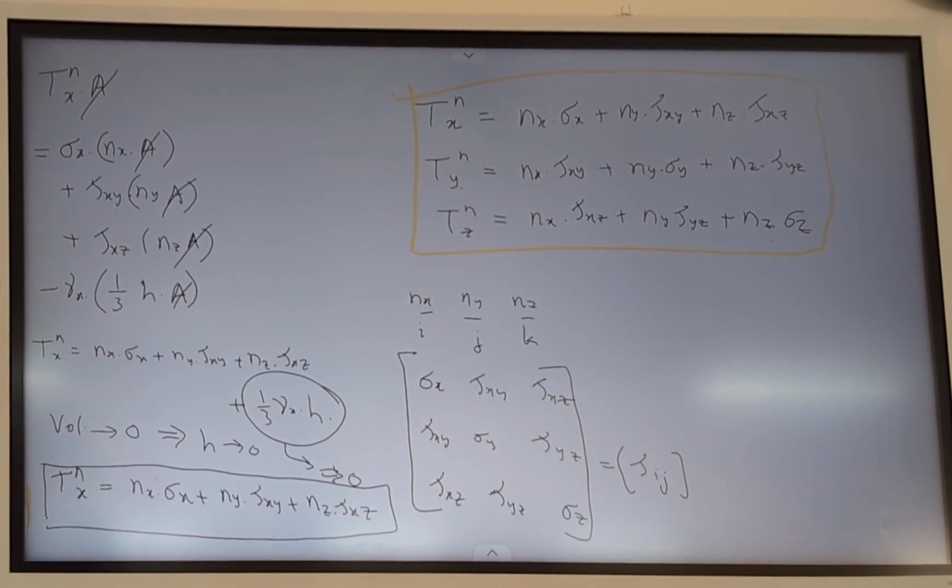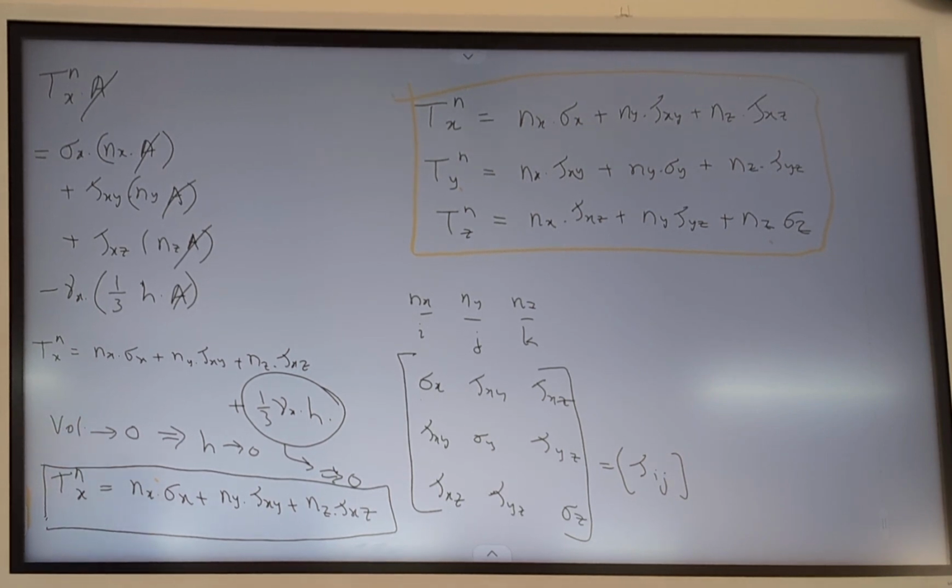One would like to know whether that joint will be able to hold the stress at that particular point. So one would like to know, along that plane, the normal traction component and the shear component. Then you can relate that normal and shear stress to the adhesive strength of the Fevicol, and determine whether it is safe or not.